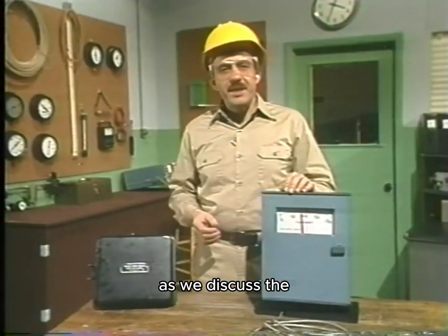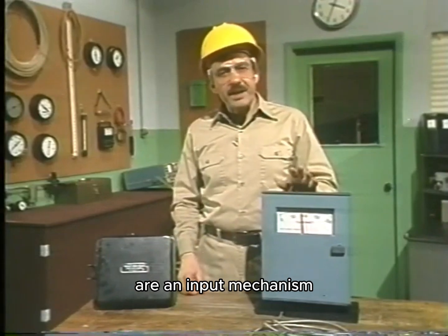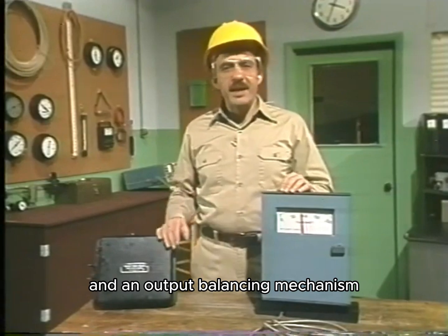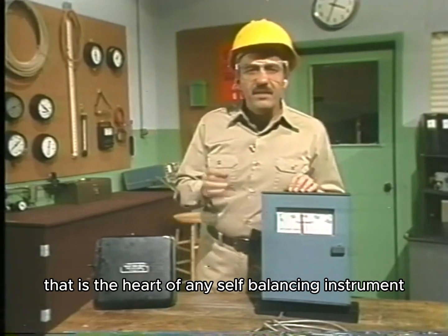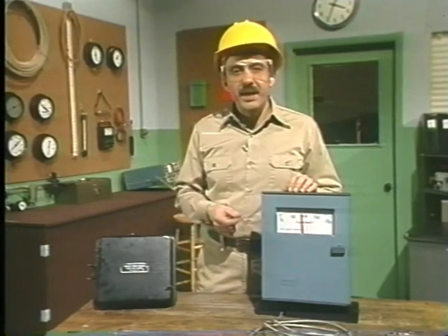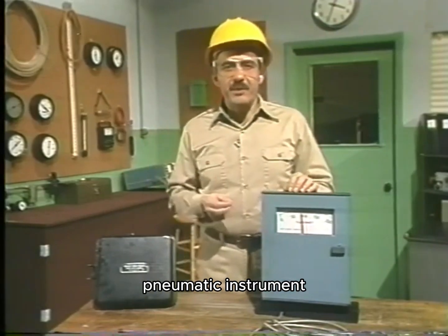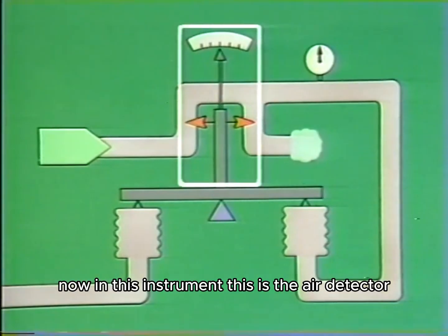As we've discussed, the essential components of a self-balancing instrument are an input mechanism, an error detector mechanism, and an output balancing mechanism. But it's the error detector that is the heart of any self-balancing instrument, whether the instrument is a controller, positioner, or transmitter. Let's go back to the illustration of a simple self-balancing pneumatic instrument. Now, in this instrument, this is the error detector.